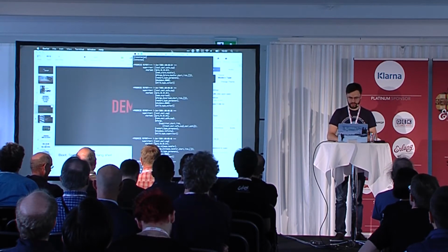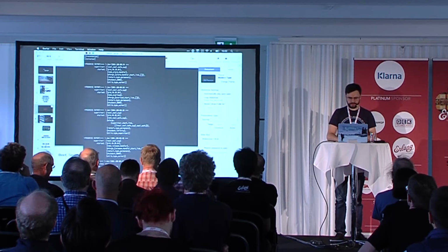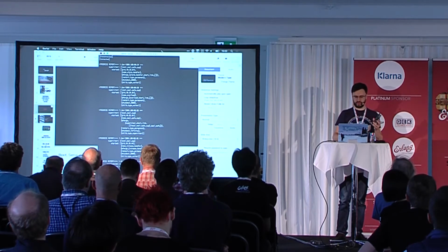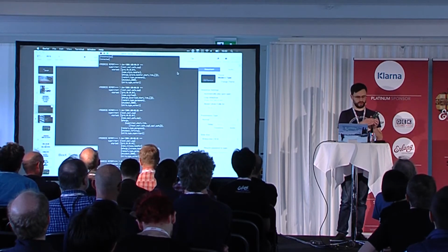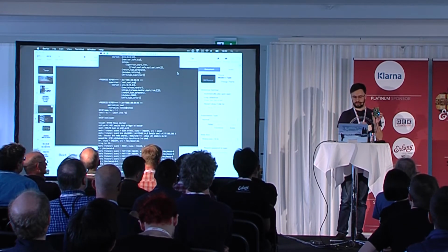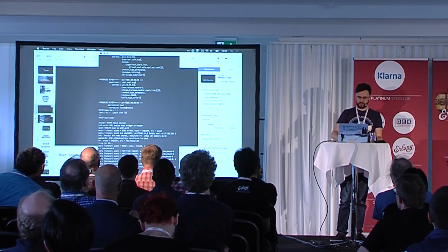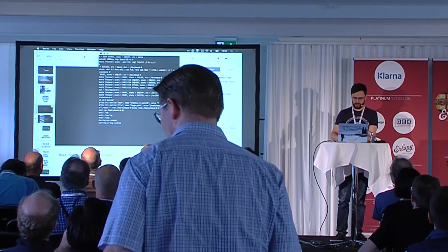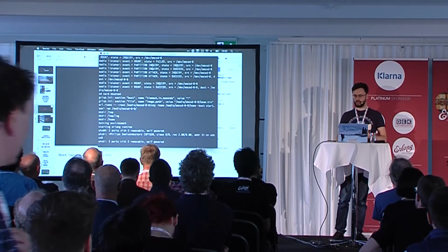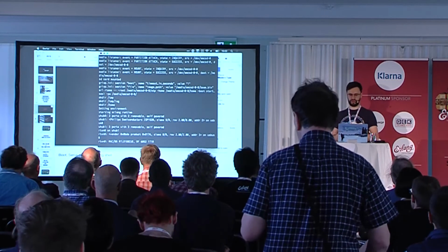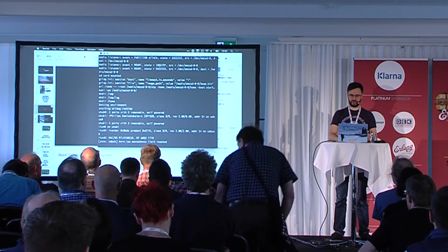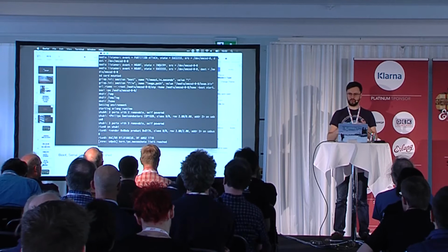So what I will show is the GRiSP board, the hardware itself. And what I will do is basically start the system. So just remove everything, press the reset button, and watch it boot. So this is what you can see in this window here. I'll make it a bit bigger. So what happens is we boot the bootloader, the low-level stuff. We initialize the hardware. And then you can see here in the middle, we're starting the Erlang runtime. And that one will boot.